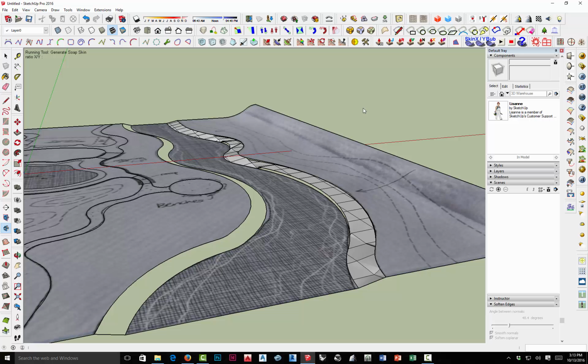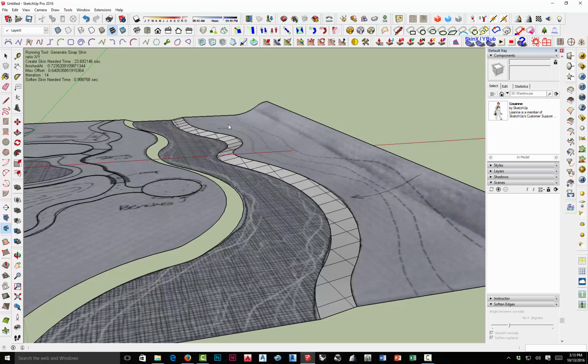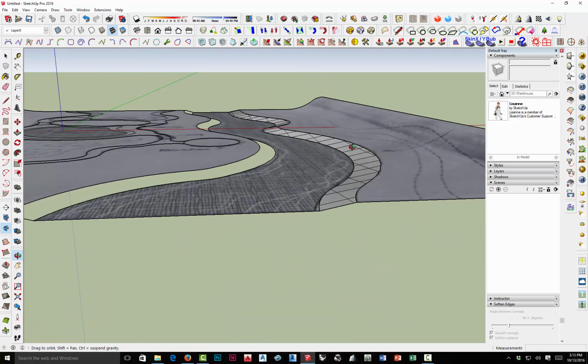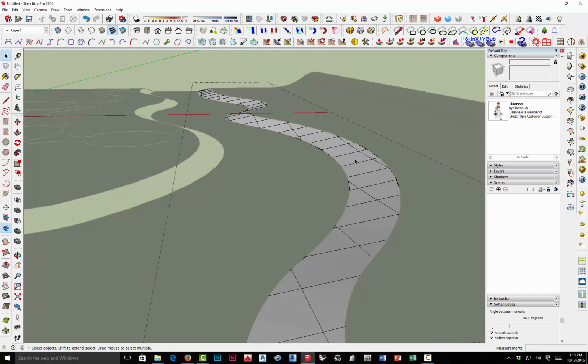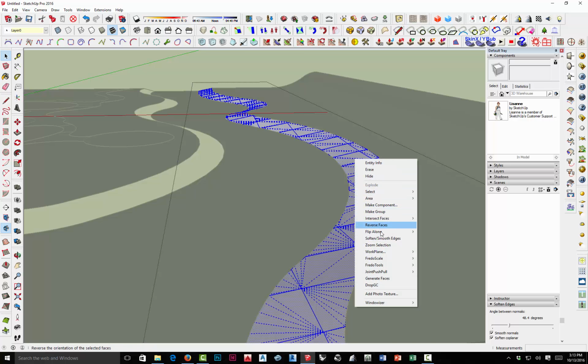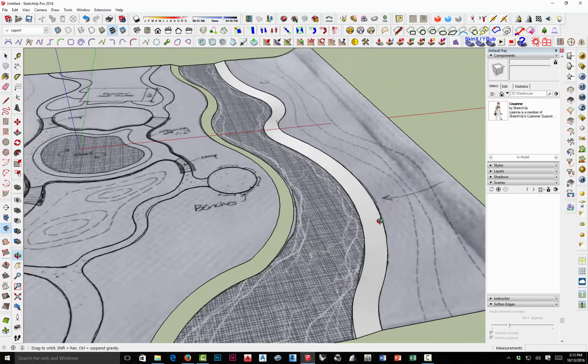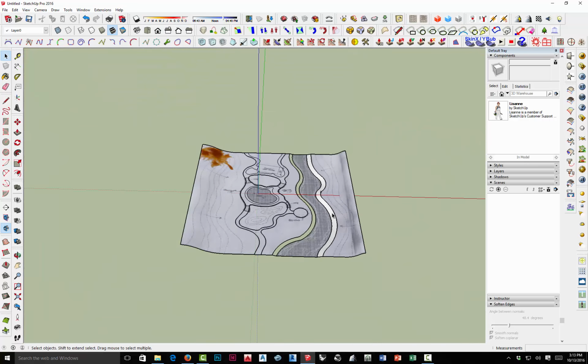It's going to keep bending and twisting that until it matches all those edges, and you'll be able to tell when it finishes. Because it will get nice and smooth just like that. Now this tool doesn't cancel itself out, so in order to start again, you need to click on the Select tool. And if we want to smooth that, like we did, let's open that up, triple click, right click, smooth, soften edges, and we're good to go there. Okay, let's do the other one.